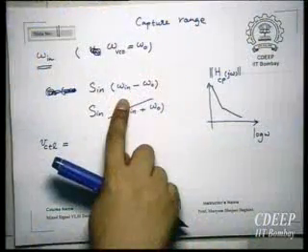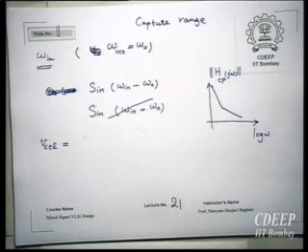Anyway, that low pass filter will have a lower gain when I have a frequency above 0, compared to the case where I have a frequency equal to 0. Therefore, in this case, the amount of voltage that is generated in the unlocked case is less than the voltage that is generated in the locked case. This is the only point that I want to emphasize.